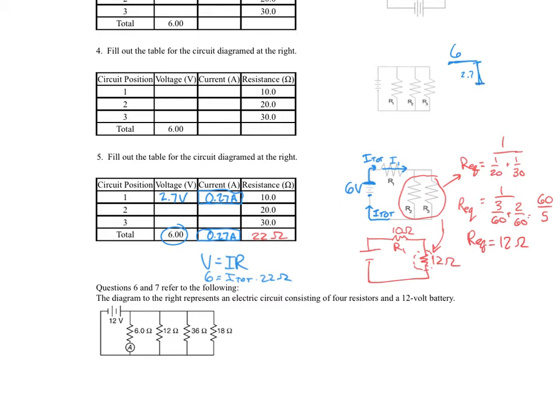So now I'm at a platform that's only 3.3 meters in the air, and to get down to 0, I'd have to change another 3.3 meters. The change here would be 3.3 in order to get myself down to a position of 0. So no matter which pathway I go down, whether it's the R2 branch or the R3 branch, I have to drop that voltage of 3.3 volts to get myself back down to 0, which is connected to the low side of the battery.